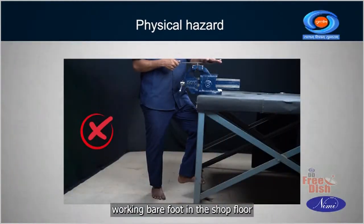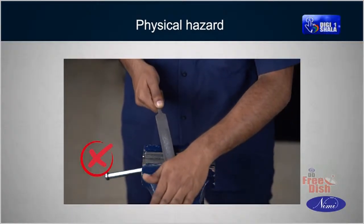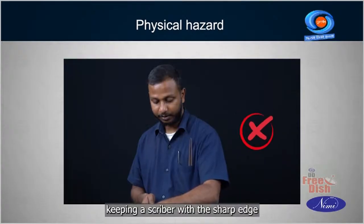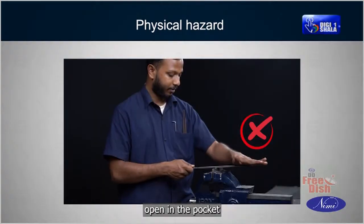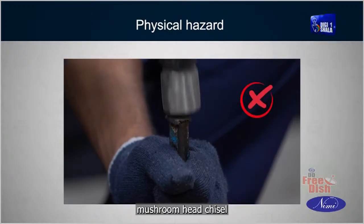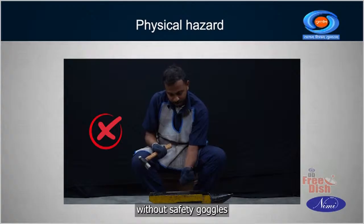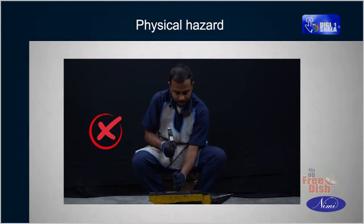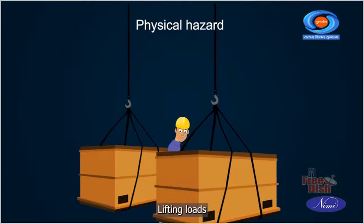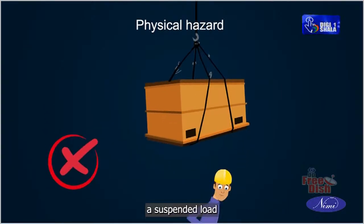There are some more physical hazards such as working barefoot on the shop floor, using a file without a handle, striking on a chisel head with a ball-peen hammer without a wedge, keeping a scriber with the sharp edge open in the pocket, chipping a metal surface with a mushroom head chisel, chipping on a metal surface without safety goggles, lifting a heavy load with damaged slings, lifting loads while people are working nearby, standing below a suspended load.